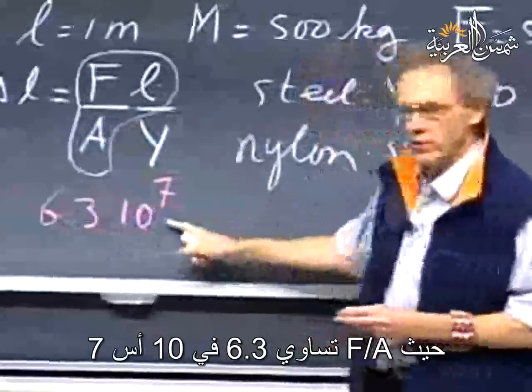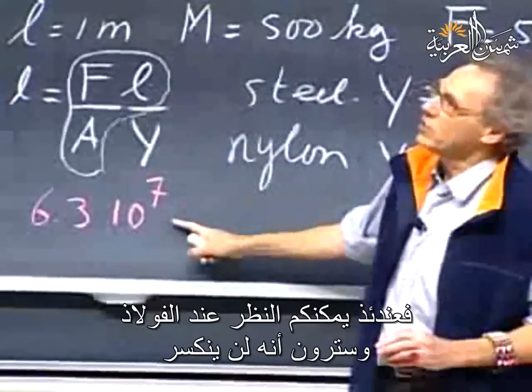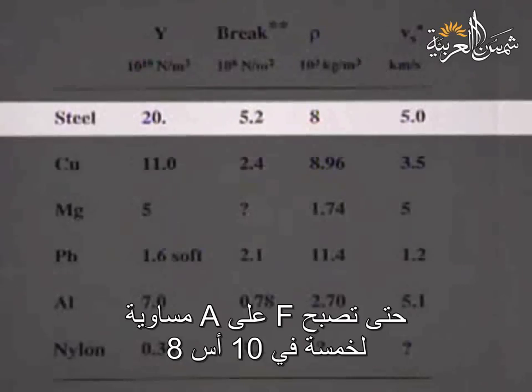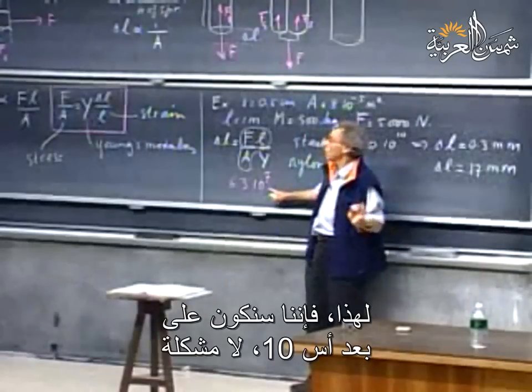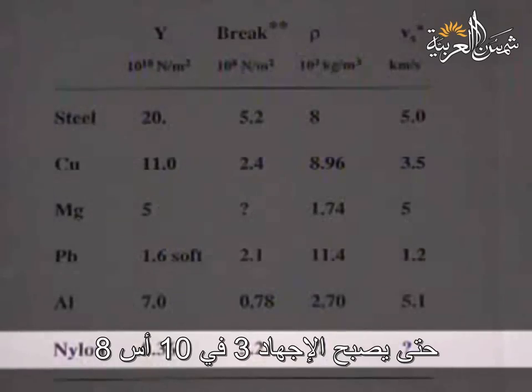If we take the case that we have here, the steel rod, for which F over A is 6.3 times 10 to the 7th, because L is 1, remember, then you can look there on the steel, that it wouldn't break. We will be very safe, because it wouldn't break until F over A becomes 5 times 10 to the 8th. And so we're a factor of 10 away from that. There's no problem. Even nylon would be very safe, because that wouldn't break until the stress is 3 times 10 to the 8th.